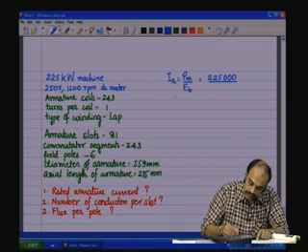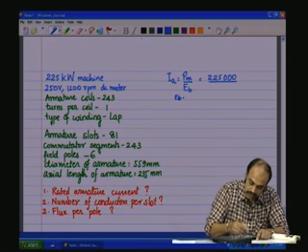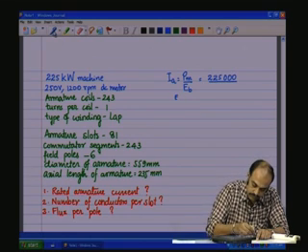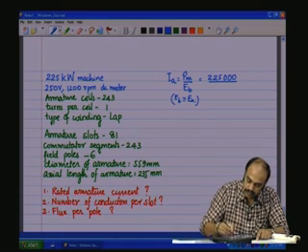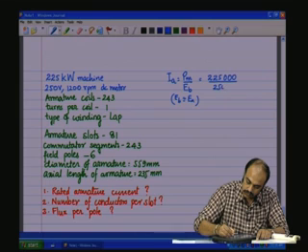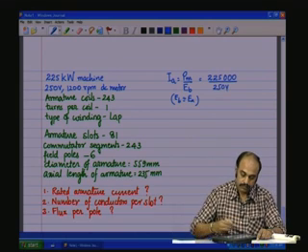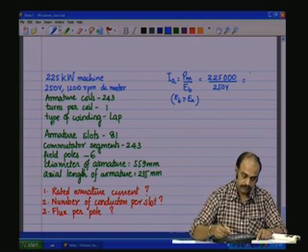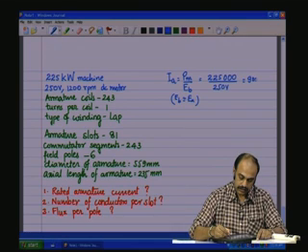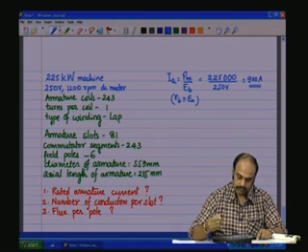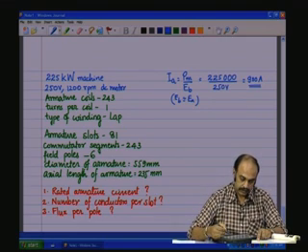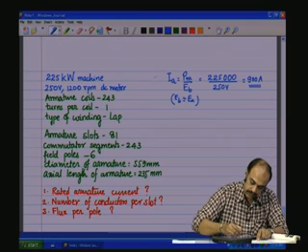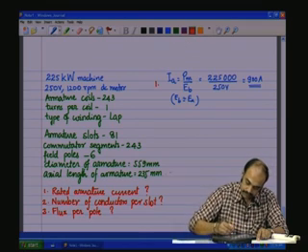So, here we are taking EA or EB is approximately equal to EA, and therefore, we say it is 250 volts. So, this will result in 900 amps. So, that would be the rated armature current. That would be the first portion of the problem.